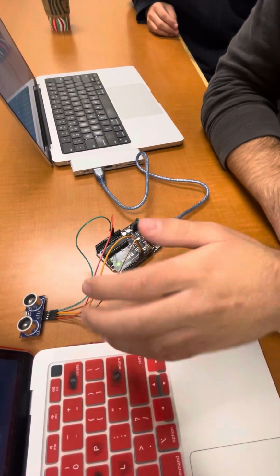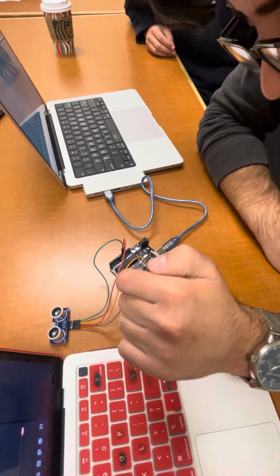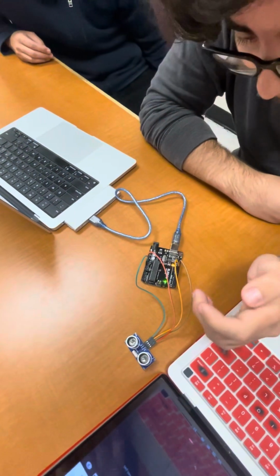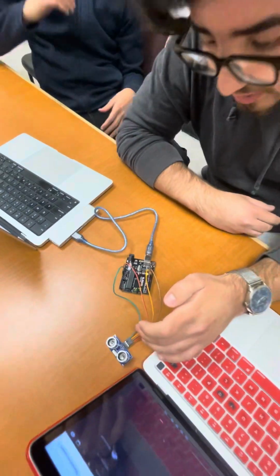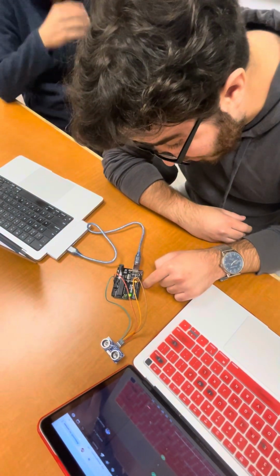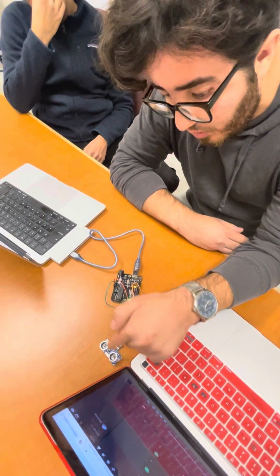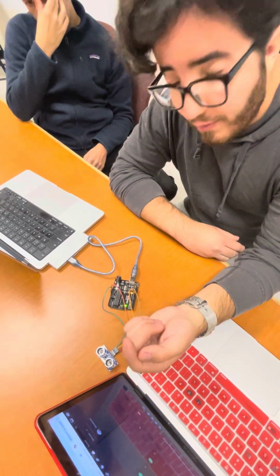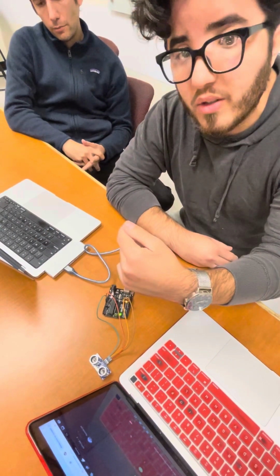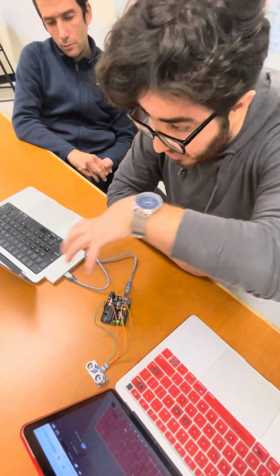The way we set it up is we connected this ultrasonic sensor to it. We connect the ground to the ground, the VCC to 5 volts, and the echo and trigger pins, which are for these two, to outputs 10 and 11. The way this ultrasonic works is one of these two sends a high frequency sound outward, and the other one receives the signal because waves bounce back, right? That's how this whole setup was made.